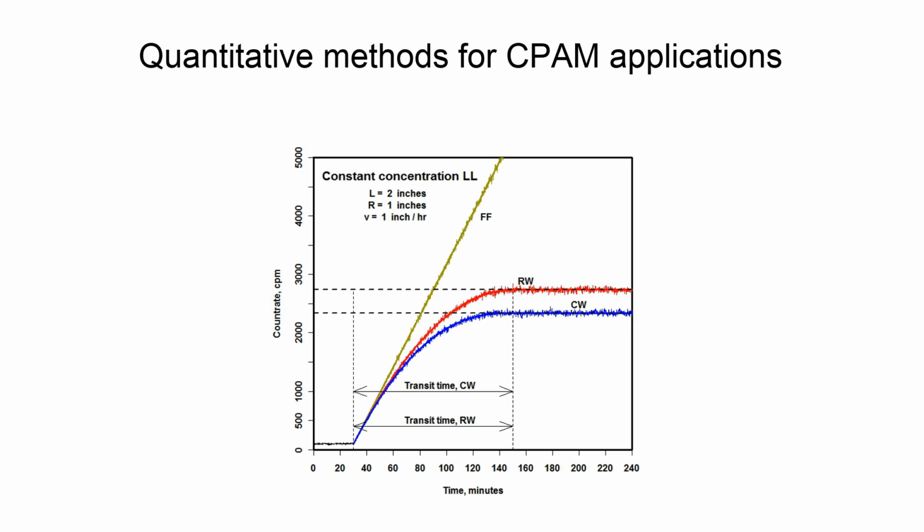An interesting subtlety to these calculations is that the time in the CPAM response equations is measured from the start of a concentration transient, so that some method of detecting the resulting change in a noisy count rate must be developed. Again, this is a good application for statistical signal processing that is made possible by the use of computing power in modern CPAMs. Which of these 11 methods to use for the applications discussed previously is not especially obvious, although there are some candidate methods that logically would be used in some applications and not in others.